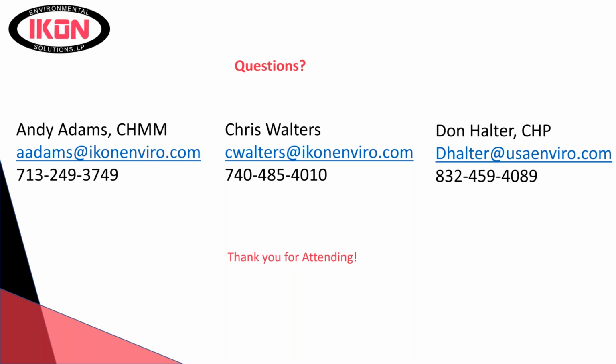So that's something we keep working on with clients, and again, it depends on how much is in there, because you don't always have the same amount of iron sulfide coming off your line. So that's one thing we always try to do: work with clients and come up with something that's mutually acceptable between the two of us. Can we mist those and put them into a drum so they're damp enough to keep the temperature down, but not so wet that you're creating 54 gallons of crud water you're going to have to dispose of at some point?